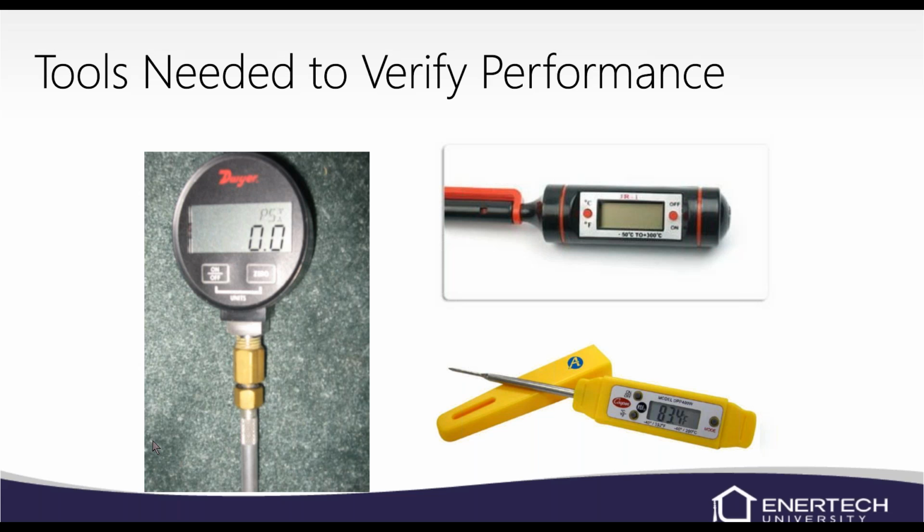The black and red digital thermometer there, we used to hand these out in trainings, but it had a really wide shaft on it, and it gets stuck in those PT ports. You've got to pull it out, and the head and the wires will come out of the thermometer and leave the shaft stuck in there. So I recommend the one on the bottom. It's a Cooper. I think I got mine on Amazon, but again, we do offer these now. And you can see the tip of that thing is kind of tapered, so it really goes into those PT ports quite nicely.